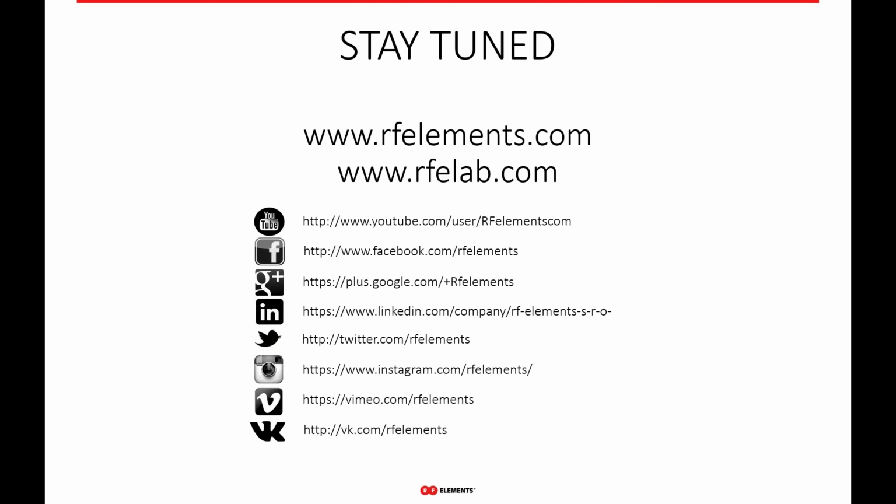So, we say this often in our webinars and in public all the time. You can't escape the design of particular antenna models. So patch array sectors have side lobes. If manufacturers tell you they have no side lobes, they're more than likely lying to you, right? You just can't get away from it. The same thing with dish antennas. Our dish antennas, the ultra dish line, have side lobes, right? So, antenna manufacturers can tell you that, yeah, you put this shield kit on it and you have no side lobes, or we'll create a deep dish versus another type of design. None of these things eliminate side lobes. They can suppress them, like we've tried to do with our patch array with the back shield, like we try to do with our particular design of parabolic dish to reduce the amount of side lobes, but they are always there.